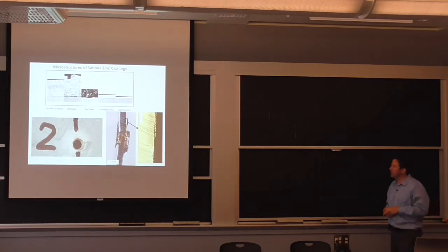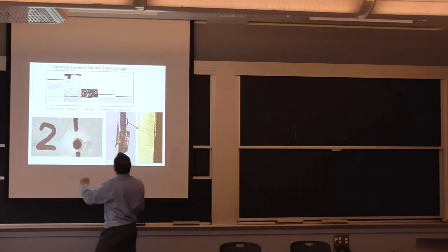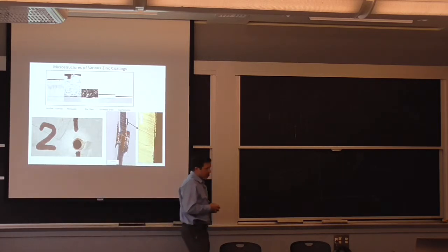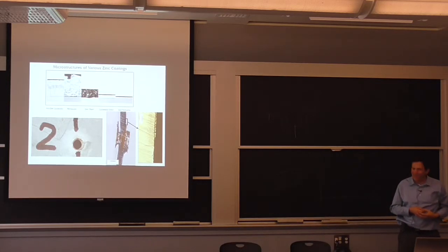Okay, so going back to the zinc here, the sample I'm circulating should have a zinc layer of one of those thicknesses. If it's hot dip galvanized, or an overlay process to create the zinc protective layer, it can be very thick. But if you look at the electroplated on the right-hand side, it's really, really thin. So if you say I'm going to use something galvanized, and then you go to Home Depot, unless it says it's hot dip galvanized, it's going to be the very thin galvanizing.